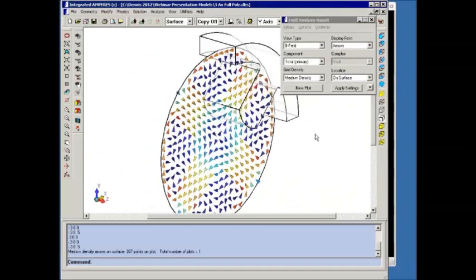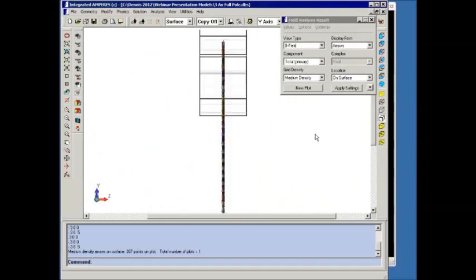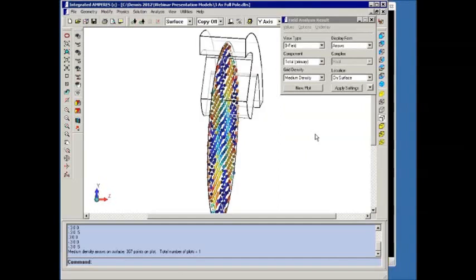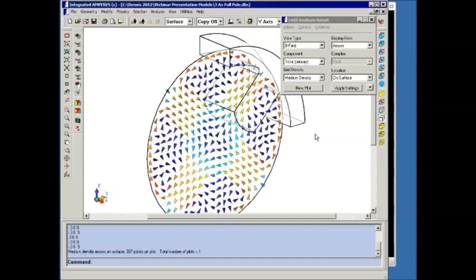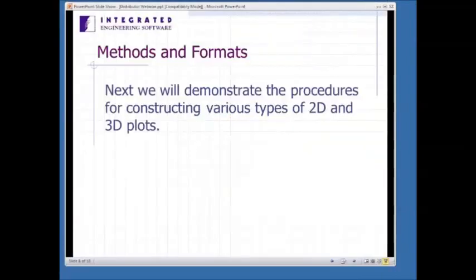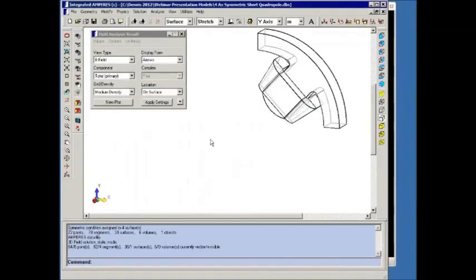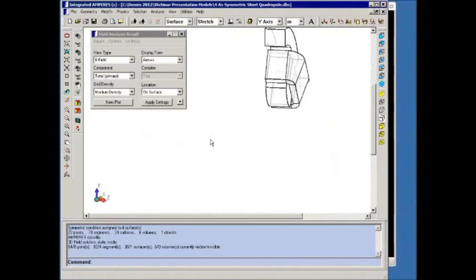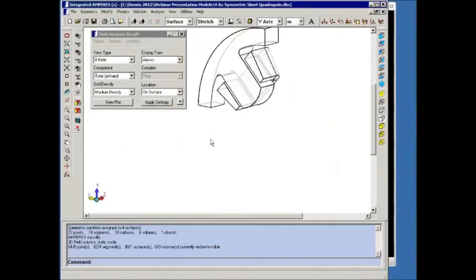Now something else we could do, you'll notice that I constructed the circular surface so that it cuts midway through the pole. Because this pole also has a symmetry plane, we could reduce this magnet model even further. We could cut it in half again and just model half of the pole and half the coils. And in fact, that's what I've done in this next model. So I'll just rotate it. So you can see, this is an anti-symmetry plane. We've cut the model in half, so we're only modeling half a pole. And that actually makes things easier.